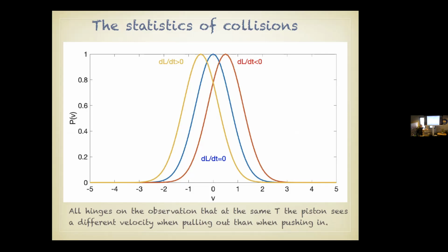But we want machines to work at finite time, so we want the piston to move, otherwise we actually have no power output. Right. And what we usually want to do is not maximize efficiency, we want to maximize power. I can take my drill and it can be very efficient if I put it in a very low gear, but then I also take a lot of time to do it, and that's the same thing.